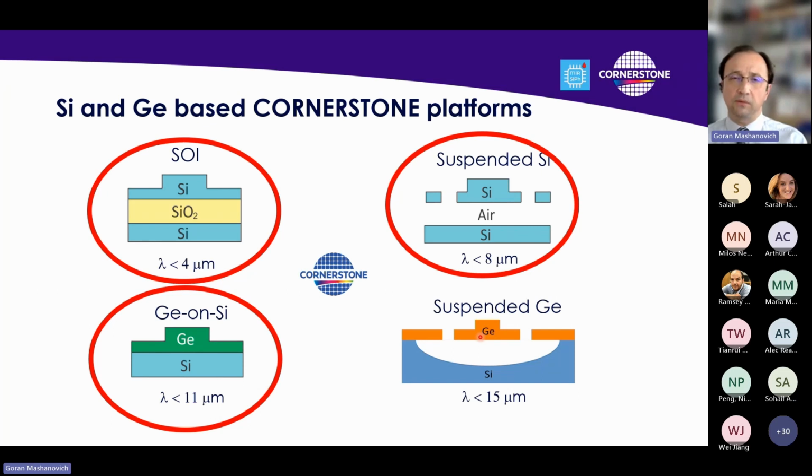And when you think about waveguides for sensing, obviously we want, in some cases, to have large evanescent field. Let's say it's gas sensing. We want the optical mode to interact with the gas that surrounds the waveguide. So confinement factor, or the proportion of evanescent field, is important.